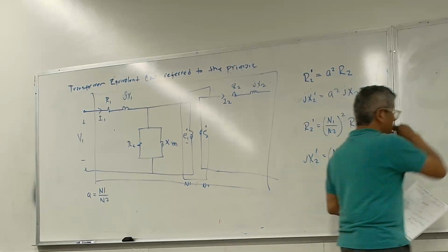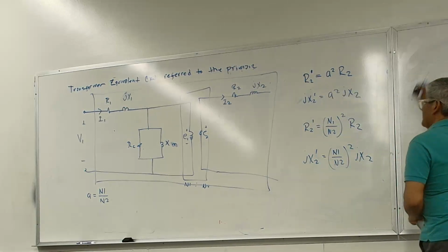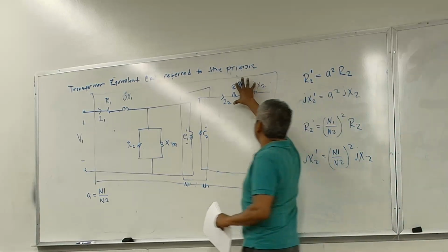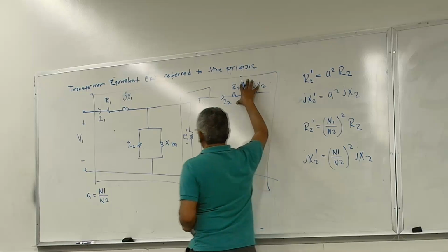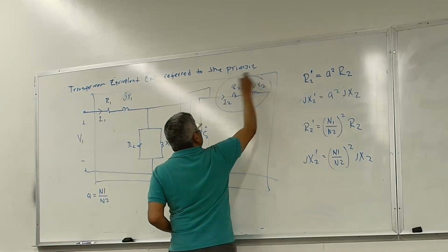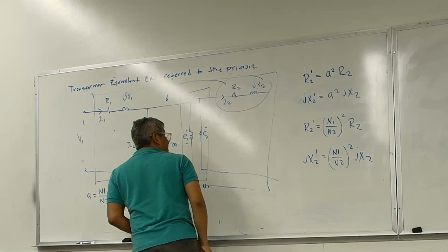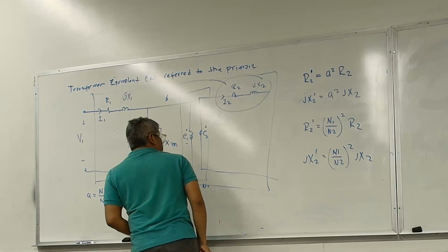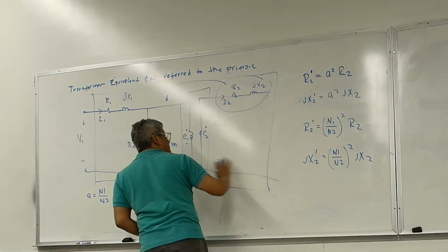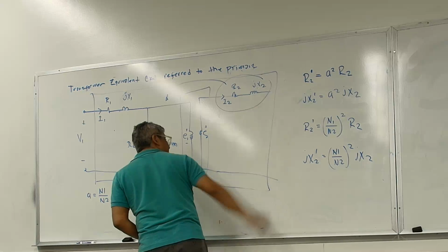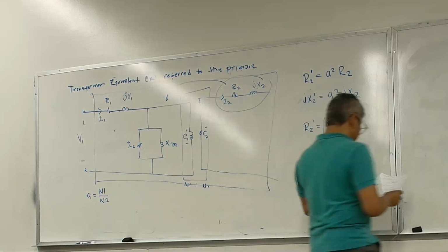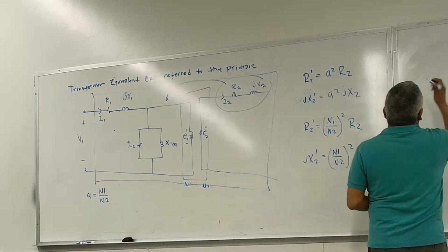Okay, so once again, we're taking this impedance and we're moving it as an equivalent circuit with the same amount of losses to the primary side, so we don't have to deal with the secondary side any longer, just like we deal with the ideal transformer. That will make it easier for us to do analysis.